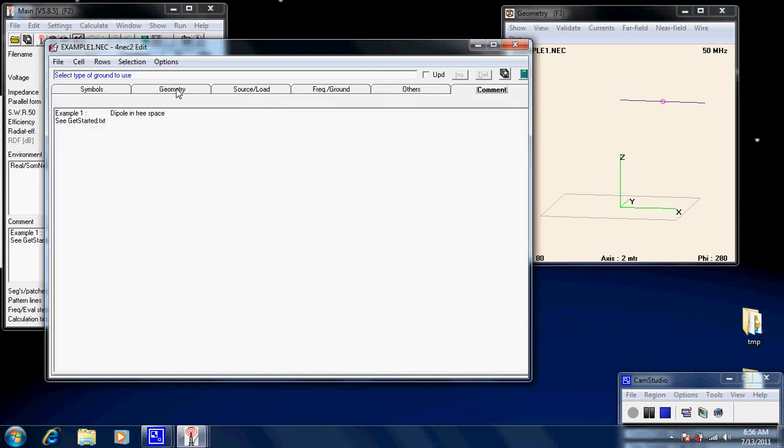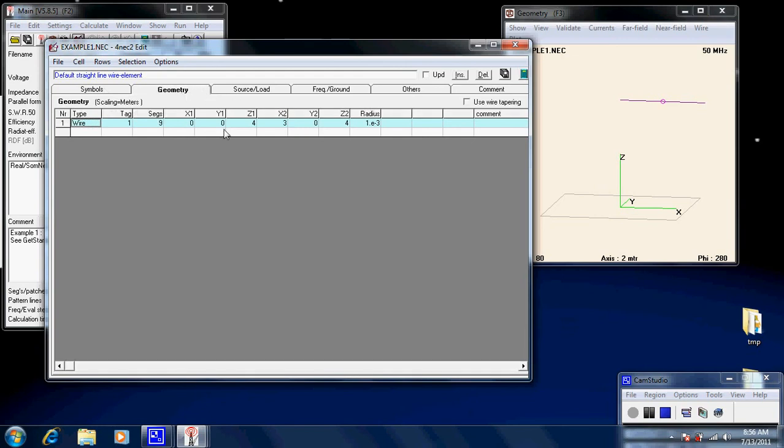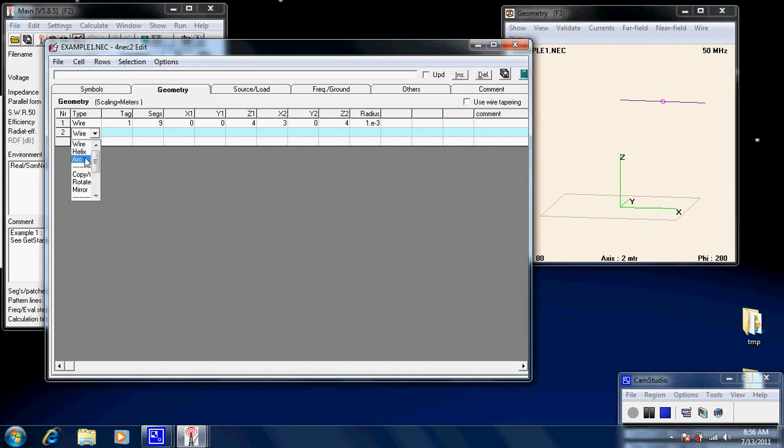Comments again. Now you can go through here and just add another one. We can put in a helix, an arc, or whatever you'd like, but let's just put a wire in. Again, we have tag 2. Let's make it 9 segments.